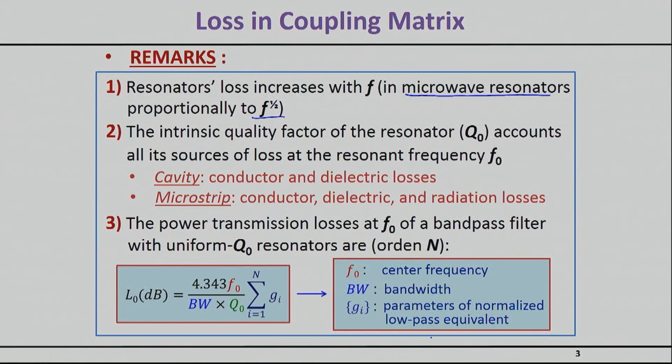And that is primarily due to the skin effect. So because the skin effect resistance changes as the square root of f, if most of your loss is due to resistive loss, then you will actually observe that type of increase. Again, unfortunately, other loss factors like radiation will also come on top of what you see basically here.